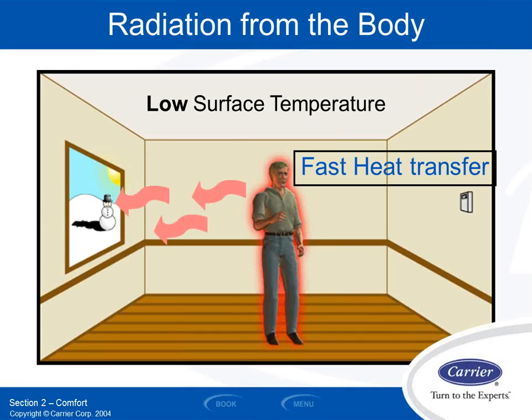There's radiation sources in buildings, right? We can have radiant heating and radiant cooling for starters, and we mechanically do stuff. But unrelated to that, in a normal building, regular surfaces in the building are going to generate radiant heat as well. So just like with the other forms of heat, the energy always goes from the hot object to the cold object, right? So in this case, this guy, his body is 92 degrees, 94 degrees surface temperature, whatever it is. That window surface, let's just say it's a double pane window and it's minus 10 outside. So the inside surface of that glass is like 46, 47, 48 degrees, something like that. So his 47 degree window and his 92 degree body, heat's going to go from the guy to the window.